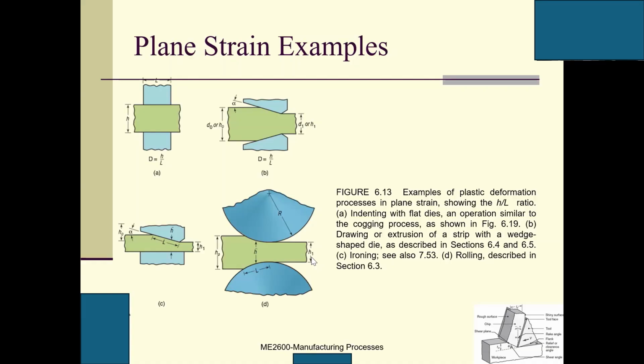Previously, in the mechanical engineering lab, we had this rolling lab. We just have a specimen. We feed the specimen between two rollers, and then the rollers rotate, and then we can see it come out compressed, processed, and then we see how the hardness changes. Because we know that we will introduce residual stress. Definitely, finally, the hardness will be much higher than the initial hardness.